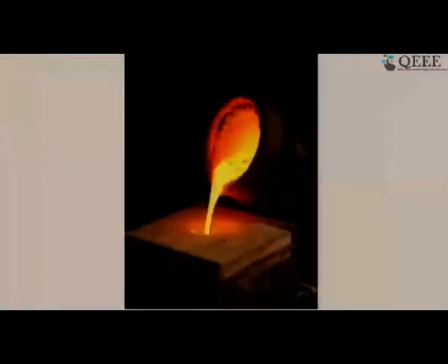with a uniform temperature everywhere. So this is the last example, and here we are looking at liquid metal being poured into a mold, and what is happening inside this is that as the metal fills the mold, there is fluid flow over there. As it goes in, it begins to contact walls of the mold which are at a lower temperature. So there is heat transfer taking place to the walls, and in case the temperature drops down to the freezing point or the melting point of the material, you start seeing a phase change gradually, which is the latent heat being taken away, and the metal solidifies.